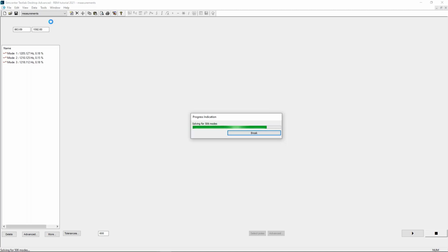Part of the reason we came out with the maximum likelihood modal model, the MLMM modal estimator, is that it might improve the data a little bit more, because that's really helpful when you have stabilization diagrams with lots of references. I should have turned it down from 600 model size before I came to this worksheet, but it's almost done.